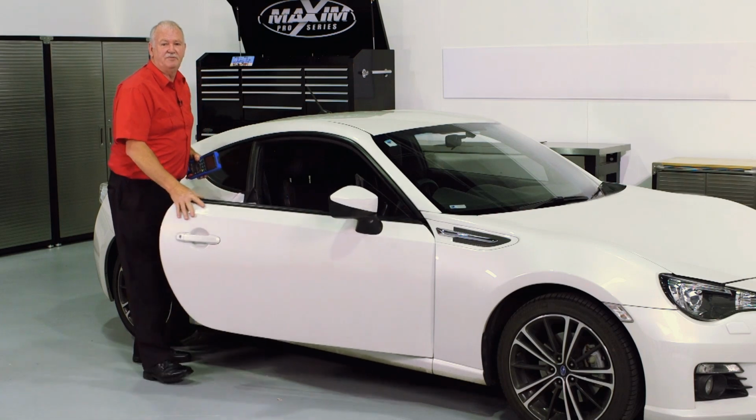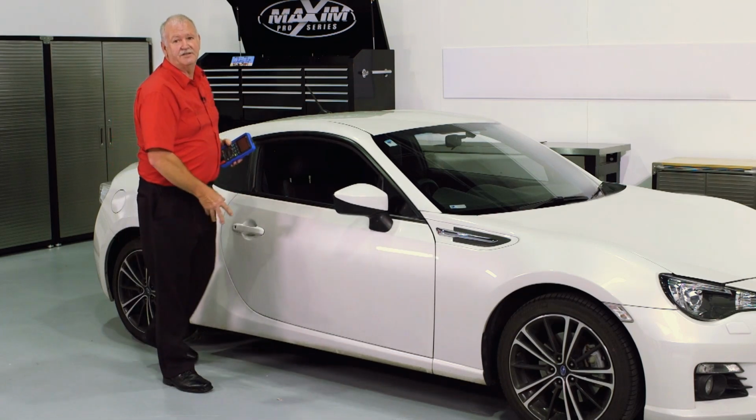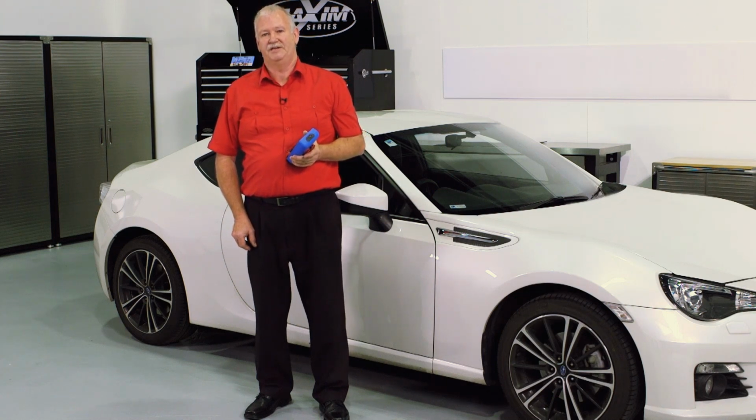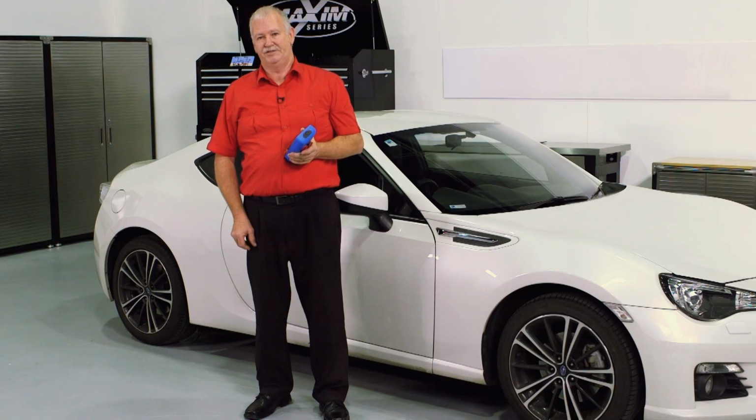And that's accelerator pedal position sensors, their circuits and how we diagnose them. We've looked at several DTCs, the most common ones, and we've looked at how we go through the diagnosis process. We've shown you how to determine whether it's a sensor or the wiring itself. Sensor faults can come in a variety of forms. If it's a contact type sensor, it might simply be the age of the vehicle. The accelerator pedal has been used quite a lot, and that's damaged the circuit. And that's one of the reasons we've gone over to a non-contact type sensor.